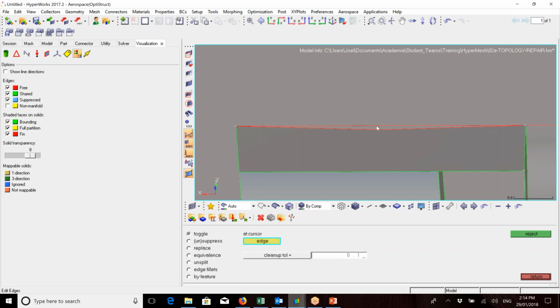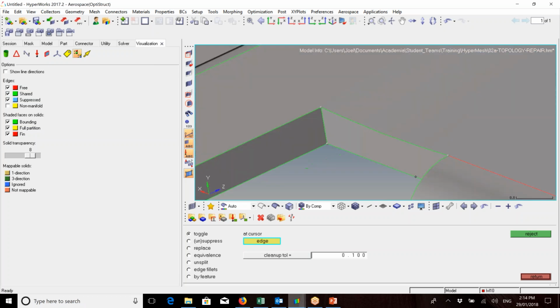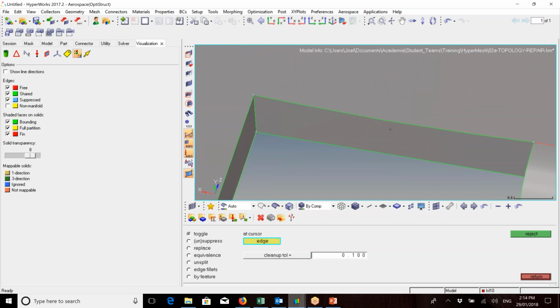All you need to do then is select the line. Double click on the line that you want to toggle. Whenever you want to go back, it's just Control Z. See, if I toggle the bent line out of shape here, the second line jumps to that. That's not the line that we want, because now we've got a little bit of funniness. So if you're not sure you selected the correct line, always Control Z, go back and just do it again.